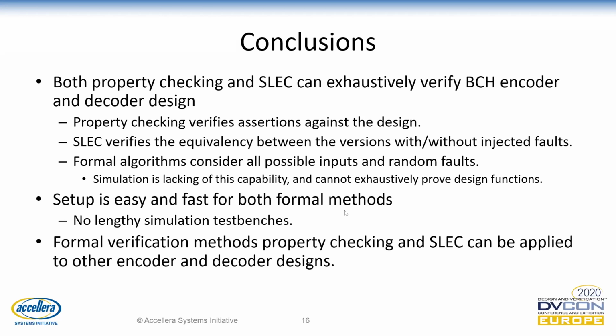Since formal algorithms consider all possible inputs and random faults, both property checking and SLEC can exhaustively prove the design functions. However, simulation lacks this capability and cannot exhaustively prove design functions. From the design, we can see the setup is easy and the runtime is fast for the two formal methods, while simulation testbenches take much more time to write. Formal verification methods, property checking and SLEC, can be applied to other encoder and decoder designs. This concludes the presentation. Thank you.